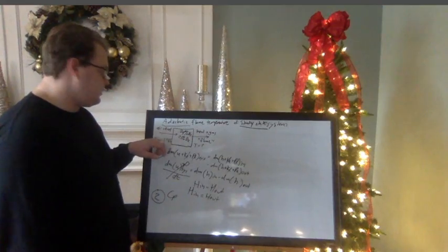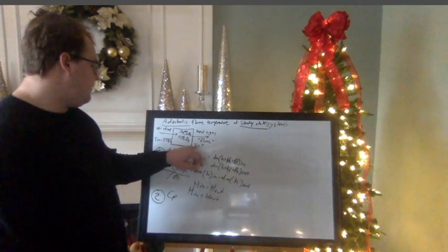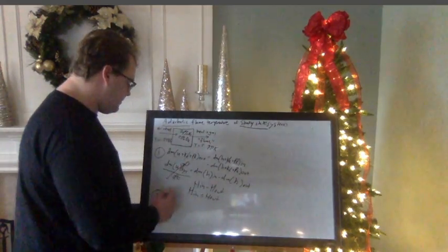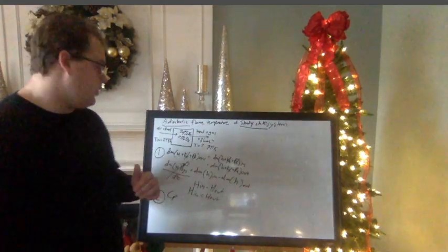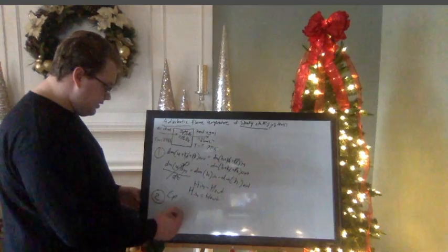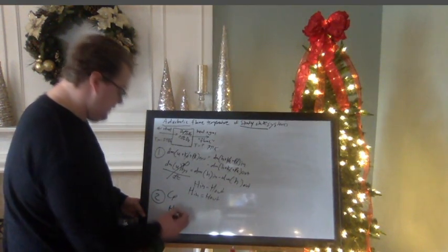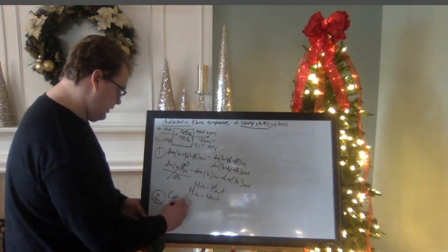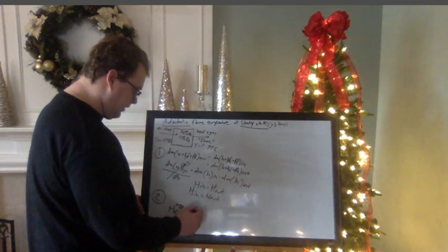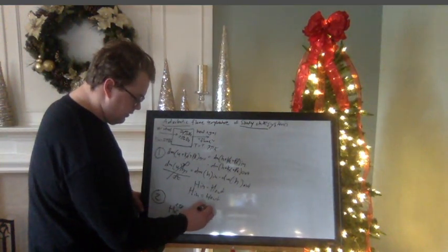And we know that this normally corresponds to a direct temperature. So there's a specific heat for a fuel at this temperature of 298 Kelvin, but there's also a specific heat of a gas when it travels to our unknown temperature. So this is going to be some super, super high temperature in Kelvin. And our specific heat isn't going to stay the same from 298 to some high number. So this needs to be a range rather than a single unit. So we're actually going to be taking the integral of this. So what I'm essentially saying here is that if we have the enthalpy of formation for our gas, that's a simplified explanation, but of our gas in this system, and we're taking it first at 298 Kelvin. Erase that for now. And then this is going to increase in temperature to some heat of formation of the same gas at a different temperature in Kelvin. So let's say this is something crazy like 3,000 degrees Kelvin.